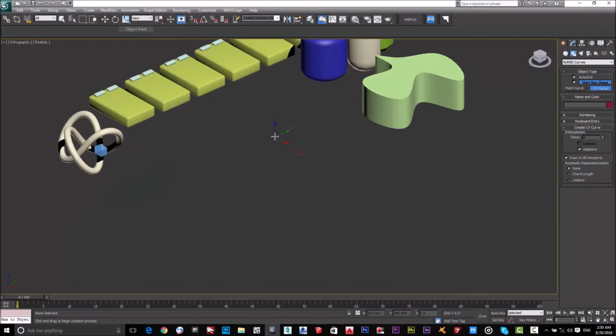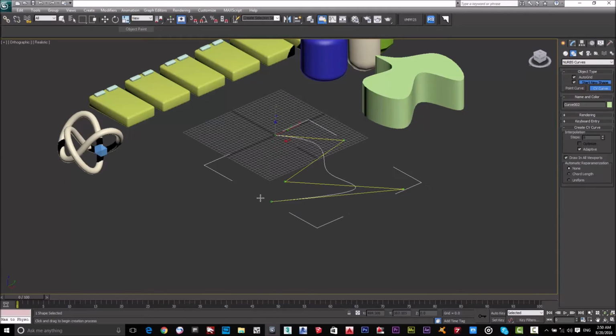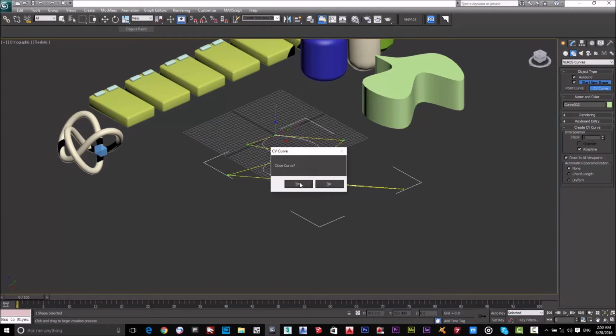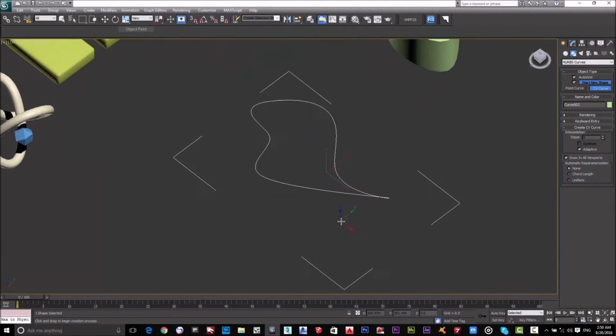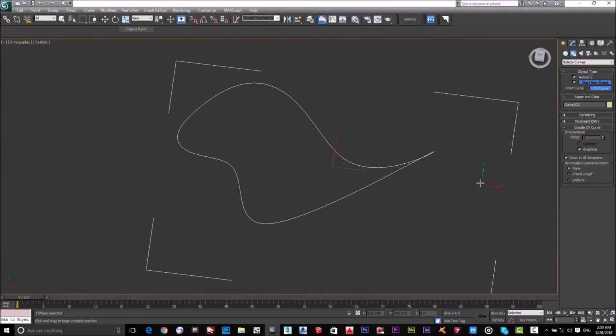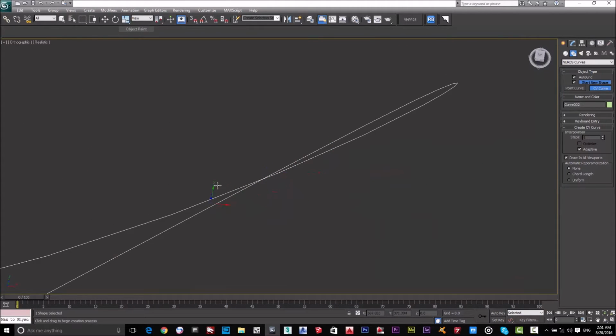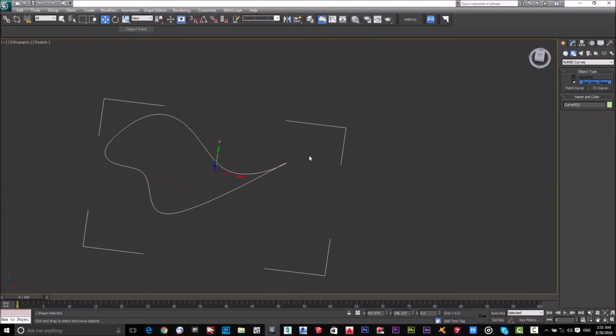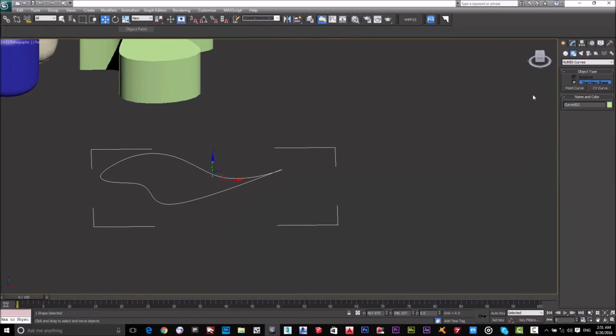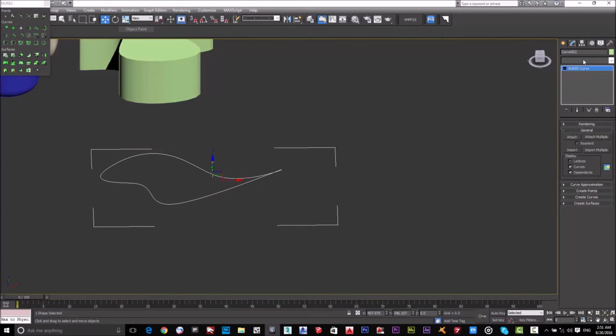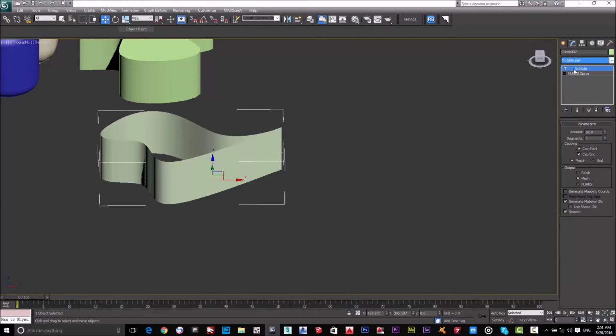I could draw a curved line like this. Then I will click again, I will click again. Now I'll close it. It's asking me as every time, so I'll hit yes. This is my shape. If you notice here, I have a problem. There's an intersection here. So I'll repeat it, because when I extrude it, I think I will get a problem. Let's try it. So EX.